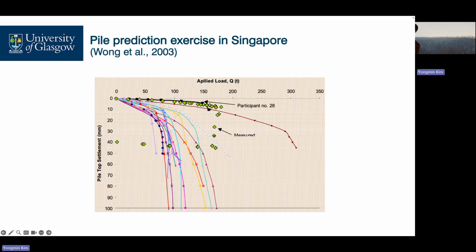See what happened. What if smaller diameter, larger diameters, shorter than initial, longer than initial length? And what if suddenly we found a clay layer? This borehole didn't detect the clay layer, but in the main column area we found clay. What should we do? Firstly, check pile behavior along the numerical simulation.